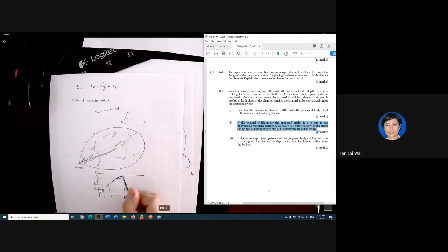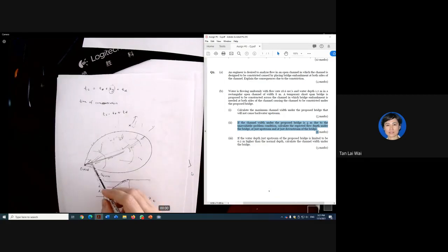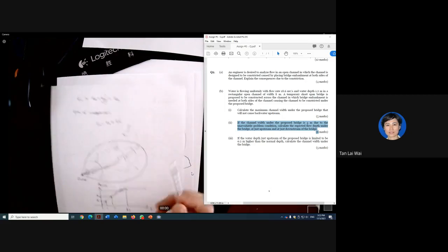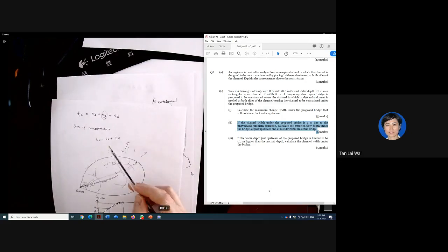The point is you want to get the Q maximum because you want to make sure the design of your drain is sufficient to cater for Q max, or peak flow, basically. So therefore, you need to determine the time of concentration. Now, when you read the manual, it will say the furthermost point to get this time of overland flow.